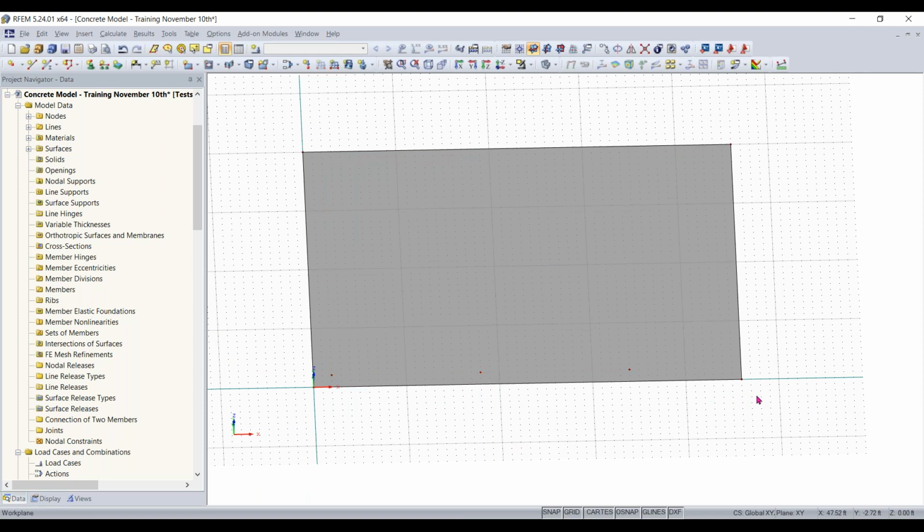And now I just have to create a 4th one. So I'll select this node, move/copy, or I could also just take this corner node here and hold Control and move it wherever I want. So I'll select it, hold Control, and then just move it to be in line with these nodes, and then 2 feet away in both directions from this corner. So everything's symmetrical.